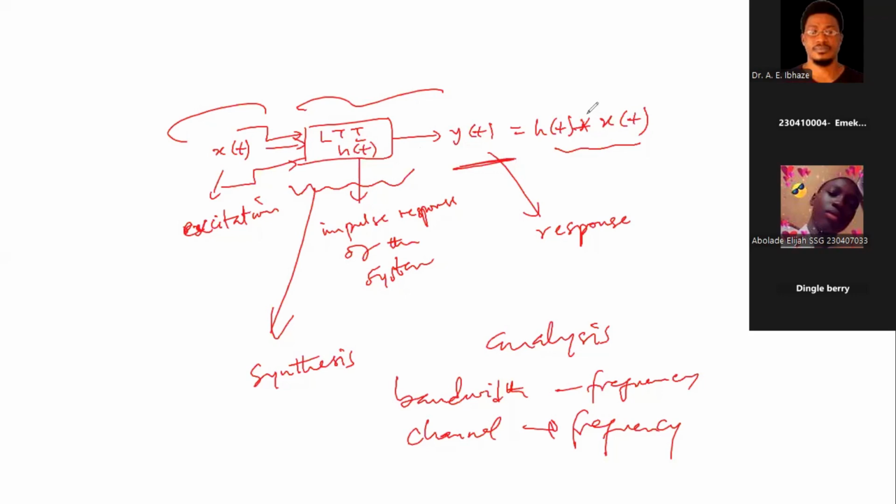I just made mention that a convolution operator is in the time domain. So this is the time domain. Now, when we go to the frequency domain, we begin to talk multiplication, right? So the signals multiply in the frequency domain. So we are now going to talk about switching between these domains. That's why we're talking about the transforms, okay? The Laplace transform, the Fourier transform, and the Z transform when we move to the discrete time domain. So we'll talk about the Z transform.